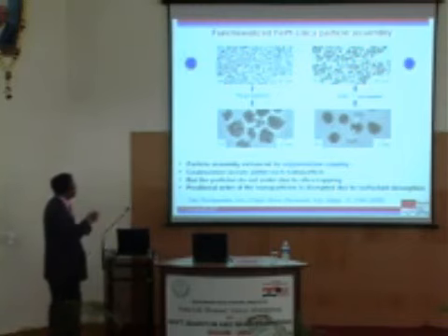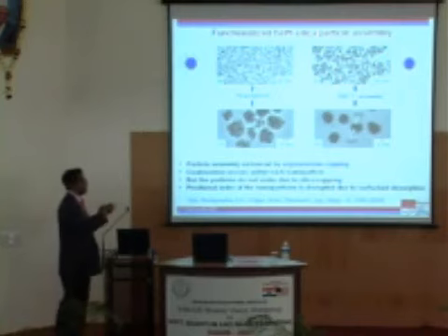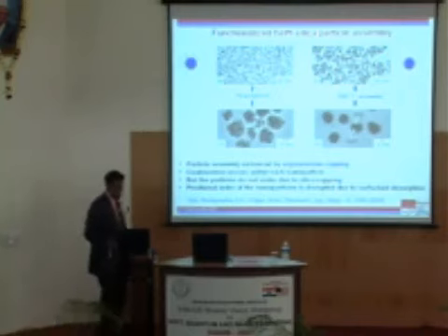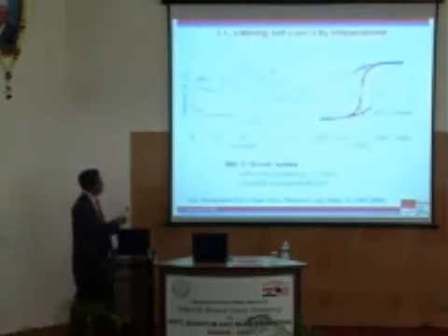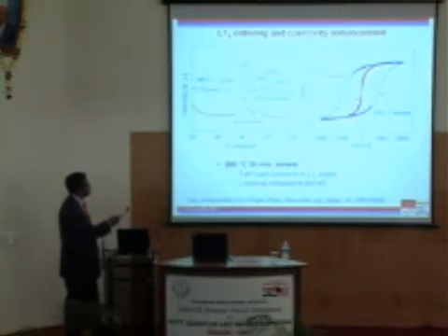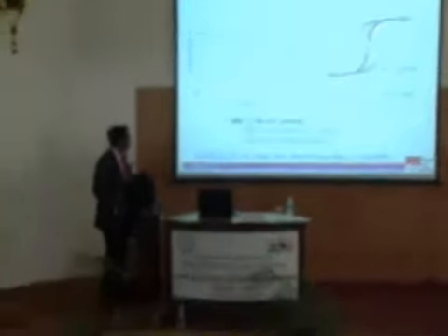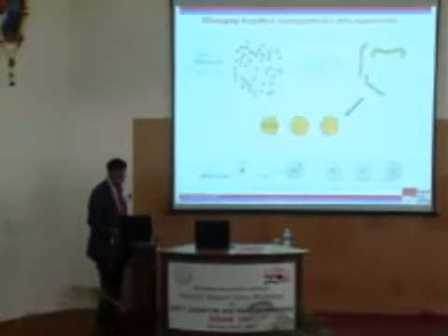The beauty here is you have, for the first time, after annealing, nanoparticles that are high coercivity and in the nanoparticle shape, where the shape is not destroyed. And that is seen over here. You can see that you get the high coercivity shown by the blue coercivity curve, whereas the red one, which is the as-prepared case, is superparamagnetic.